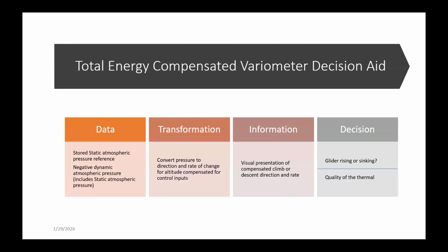So the TE probe, or TE vario, measures the variation of the glider's total energy. So it's the rate of gain or loss corrected for the glider's airspeed. It's the actual change rather than just the change from exchanging speed and altitude. It will indicate the actual rate of sink corresponding to the actual velocity and according to the glider's